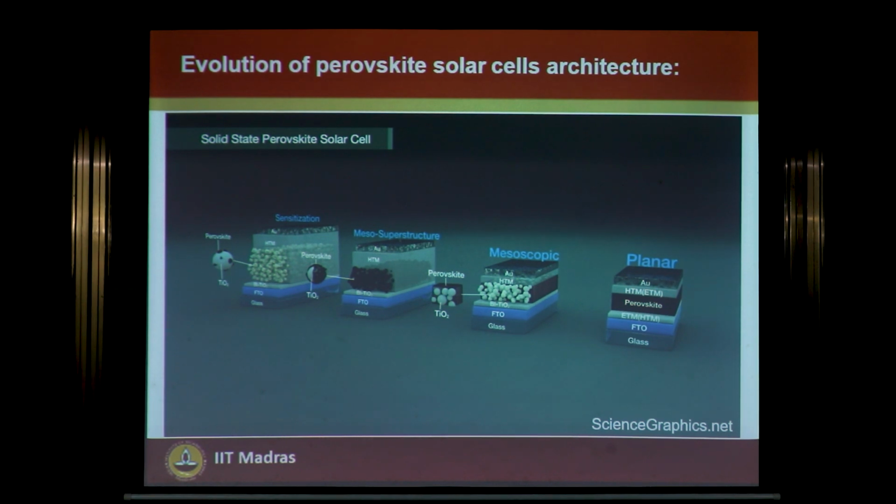The field is mostly driven by diffusion of charges. It's not the drift which is moving the charges away. And later on, once the built-in field kicks in, then the drift starts. That's the idea behind that. And the film thickness is like 400 nanometers. So it absorbs everything because of the very high absorption coefficient.